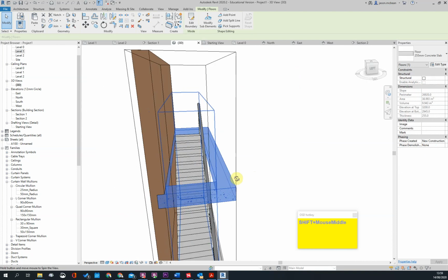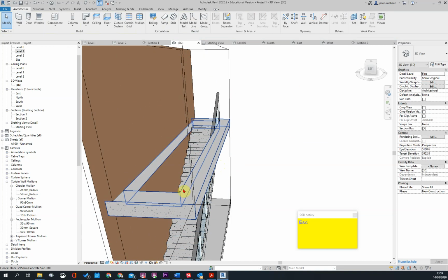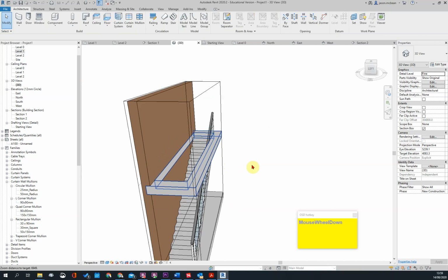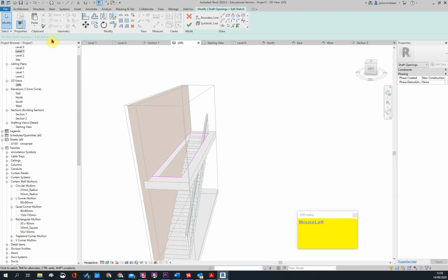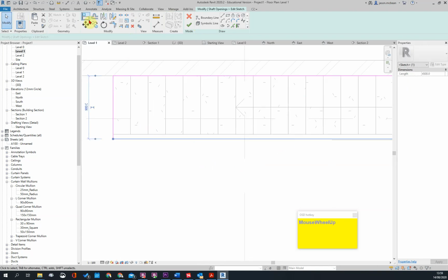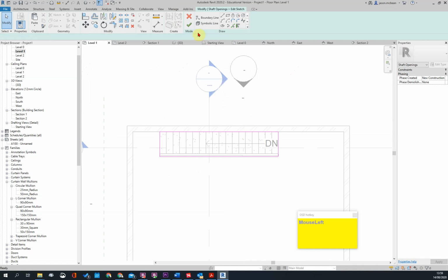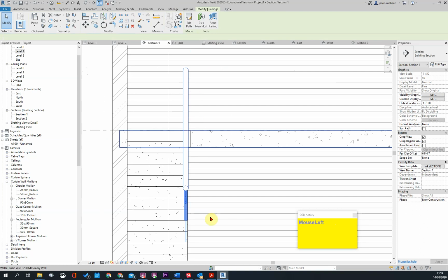Generally, we try and leave a nice gap because your hand has to go through a gap there. So generally, if we select the shaft opening, which it should allow me to select in a minute, sometimes it won't. Go to tab, tab, tab. Now you'll have to go to, there's the shaft there. So edit sketch. Okay, so here you might have to move this again by another 60 mil, this side by 60 or 50. Okay, finish. Because you need the hand railing to go past.